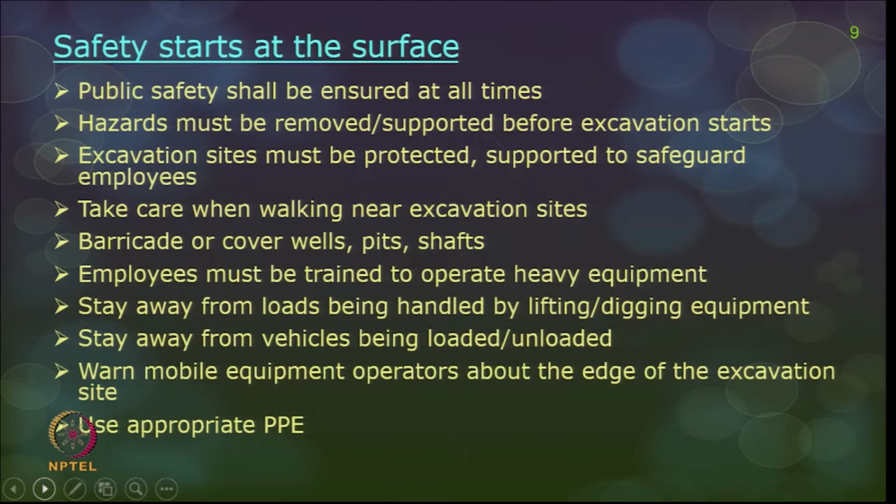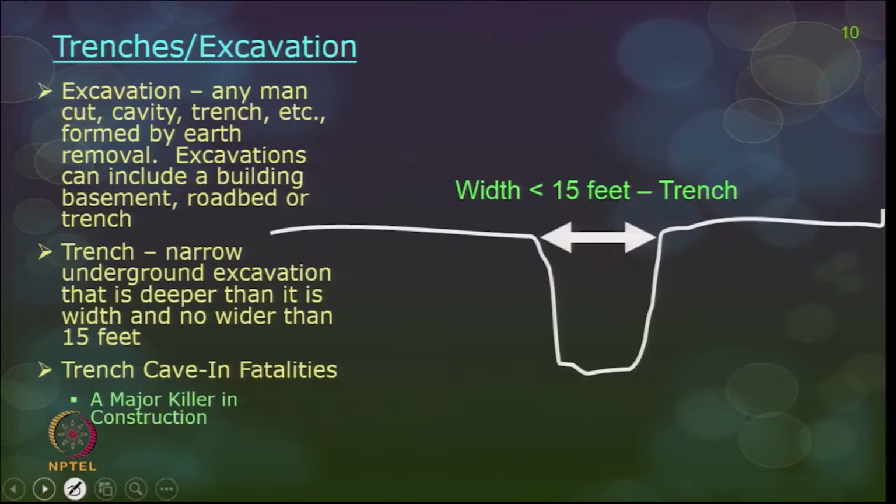When mobile equipment is operated close to the edge of the excavation site, you should stop those processes, because the vibration of that equipment can disturb the soil which you have cut. Use appropriate PPE. These are generic steps which you should keep in mind before you start with your excavation. Now, let us talk about the actual excavation and where cave-ins are more likely.